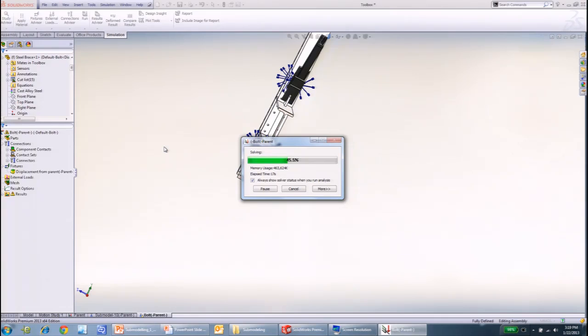Yes? What's your favorite way of handling welds? That's a good question. You can use a submodel. You can add the welds just in the submodel, and then you would have the load path go through the welds rather than the plate. So if it's bonded between the two plate faces, you'll make it free, but bond the welds on both sides.